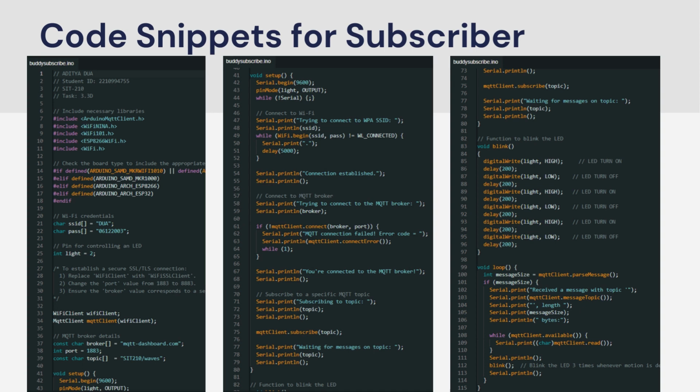In the setup function, the code first initializes serial communication for debugging purposes. It then configures the specified LED pin as an output to control an LED. The function proceeds to establish a connection to the designated Wi-Fi network, and it patiently waits until the connection is successfully established. Finally, it attempts to connect to the MQTT broker, and in case of a failed connection, it outputs an error message and enters an infinite loop, ensuring that the program does not proceed until a successful MQTT connection is established. A custom function named blink is defined to blink the LED 3 times with a 200 millisecond delay between each blink.